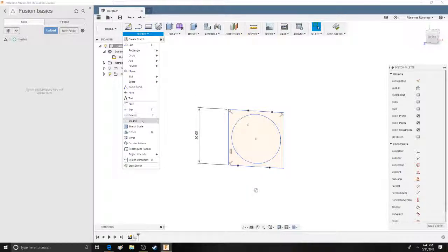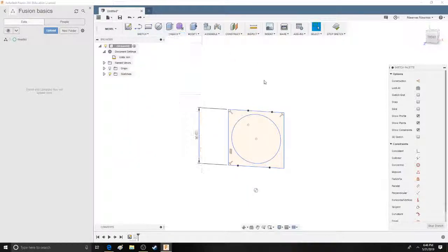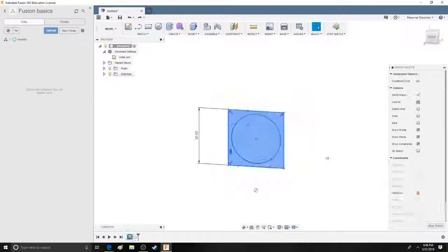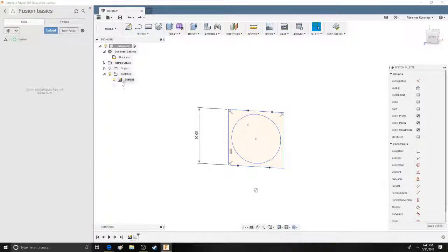So, let's see. What can you do with a sketch like this? Well, if you're just starting off with a sketch, you just have a flat sketch. It can be exported into an STL file or DXF file. Let's say you want to laser cut it or get it fabricated in another way, such as vinyl cutting. You can export it as a DXF. You can also slice the sketch, which means it slices across a 3D model. So how would you go from sketch to 3D model?